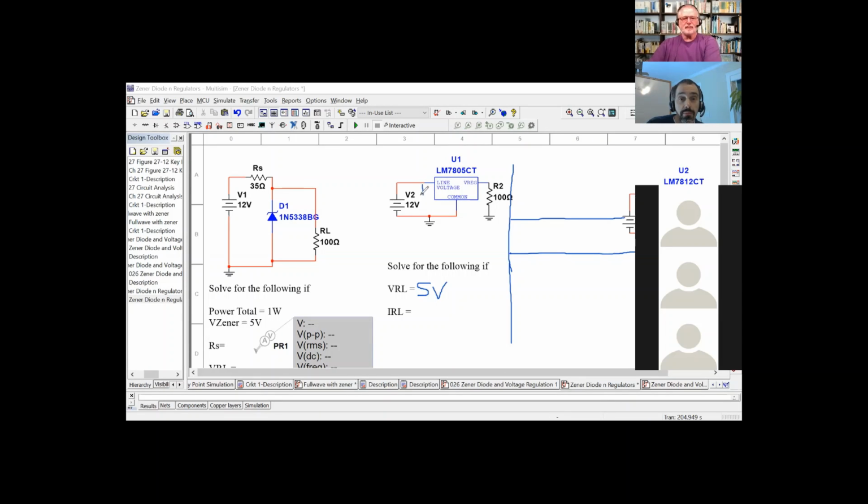Capacitors, right? A big capacitor right here. And we also sometimes put a capacitor on this end of it. What that does is give it a little more stability. So this could be about a 1000 microfarad, and this one would be like 4700. So that's just like what you have.